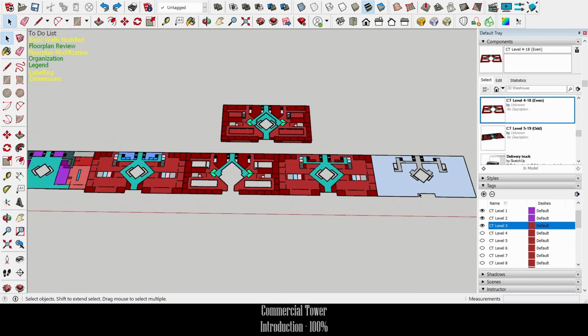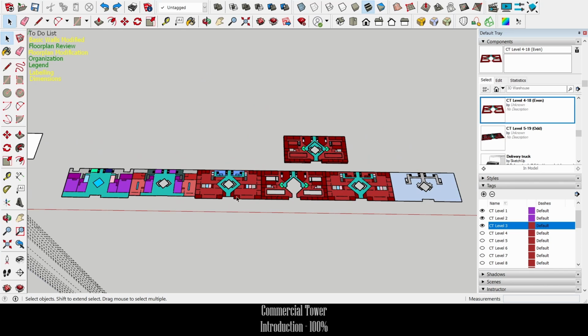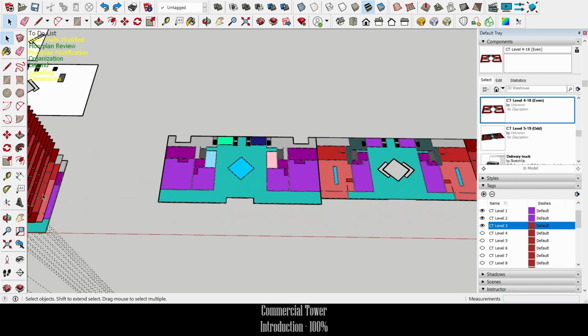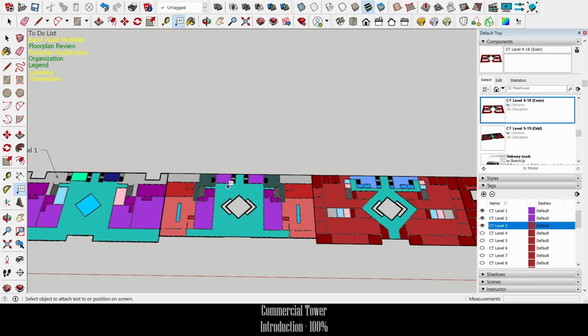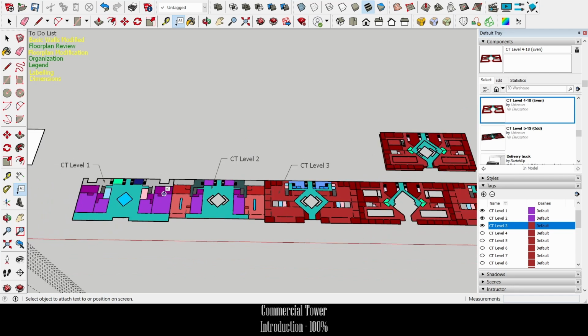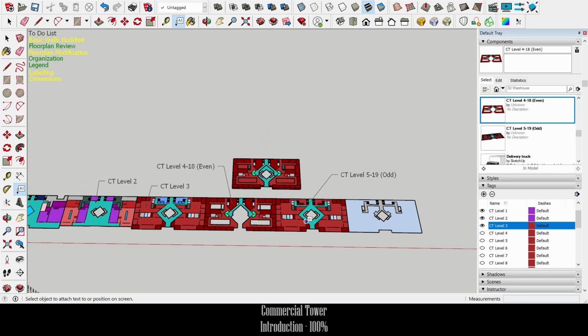Now, you may have noticed a few sort of unusual things about the model, and I think the first is all of the bright colors. The reason it's covered in bright colors is because in SketchUp, I prefer to avoid using the labels provided by SketchUp to label specific rooms, and I prefer to use color coding simply because, for one, I think it's a lot more intuitive.